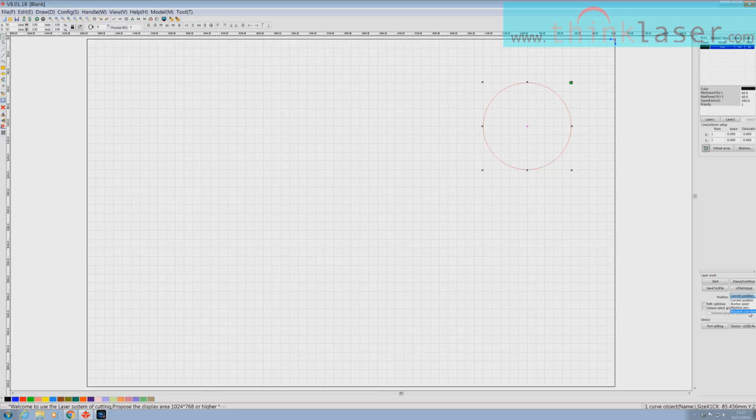One of them is absolute coordinate. That's a very useful feature sometimes. If I save my program with this save to U file with the drawing like this, then I shall not get the option on the machine to move the datum around and press the origin button. You've specified absolute coordinates, so what that means is the circle will get drawn there and only there in relation to 0, 0. You won't have any chance of moving it around on the workpiece.